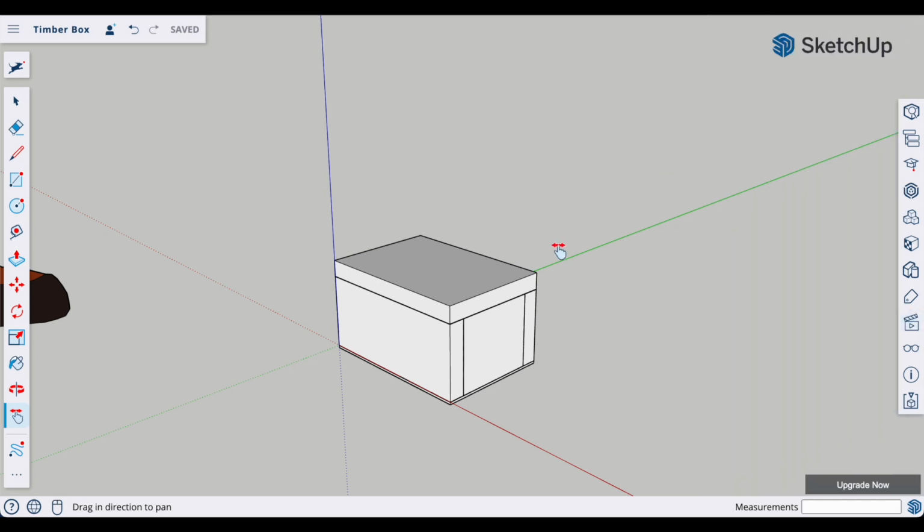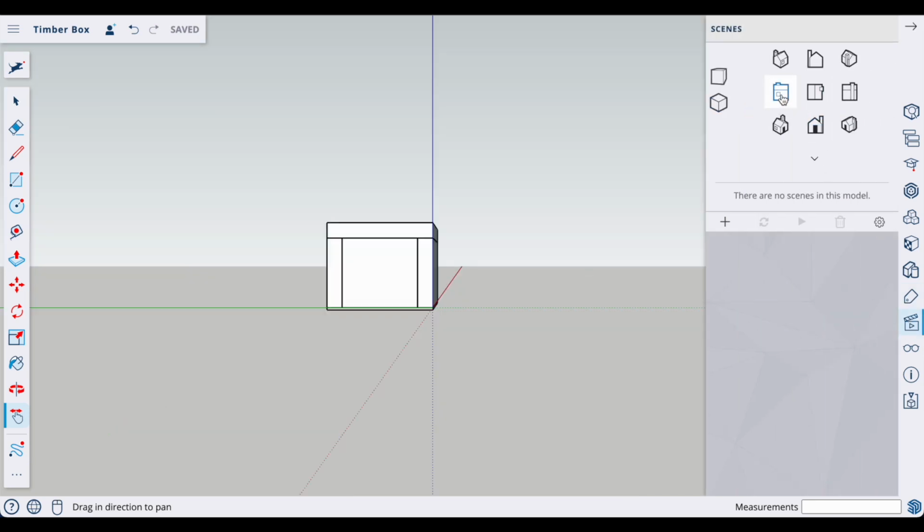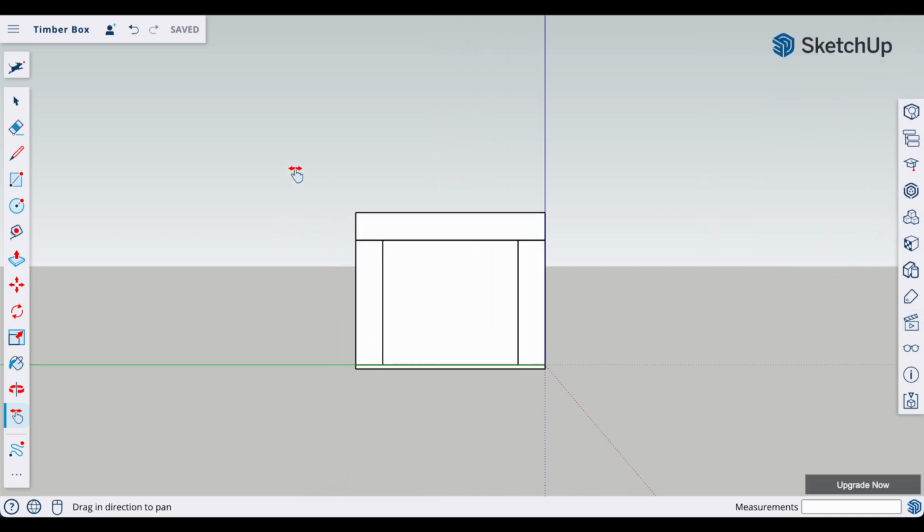Now the last thing we'll do for this tutorial is to tilt the lid open and show you the rotate tool. So what we'd want to do now is, using those views that I just showed you, go to one of our side views. So you're looking at it from the side, close that panel, zoom in. Down on our left-hand toolbar, go to this icon here, rotate tool, shortcut is Q.